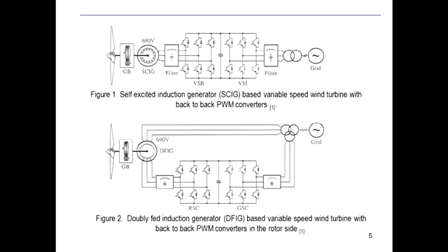And then there is another kind of induction machine where the excitation can be in the rotor, all right, not in the stator. Stator gets connected to the grid directly, but we have a back-to-back. This is an inverter, and this is a PWM rectifier. The roles have reversed. This draws DC power from the grid with unity power factor and develops a voltage across it. And this inverter then produces current in the rotor, which excites the field. All right, and then the machine will act as a generator. Now, in this scheme, the converter rating is less than 1/3 of this converter's rating. These 2 converters combined handle only a small amount of power, all right, much less than these converters require.